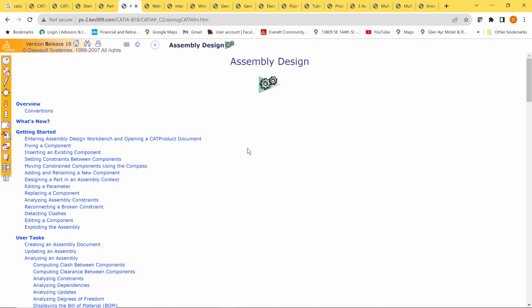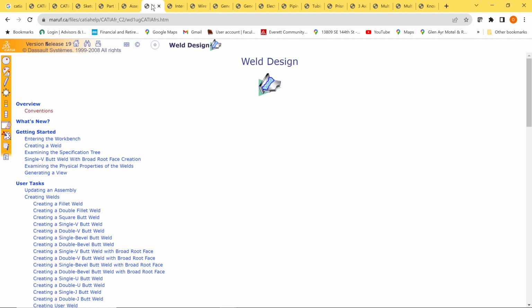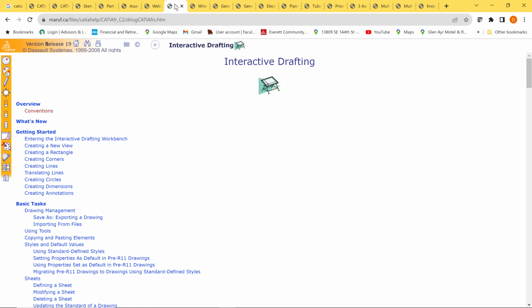Once you have two parts and you put it into one model, that becomes an assembly. So once a plate is bolted onto something or you got a press foot bushing, you instantly have an assembly because there's more than one part. Unless they're being welded together, in which case if it's a weldment or two parts welded together, it's called a weldment. So we'll show you how to make drawings of the detail parts, assemblies, the weldments and such.